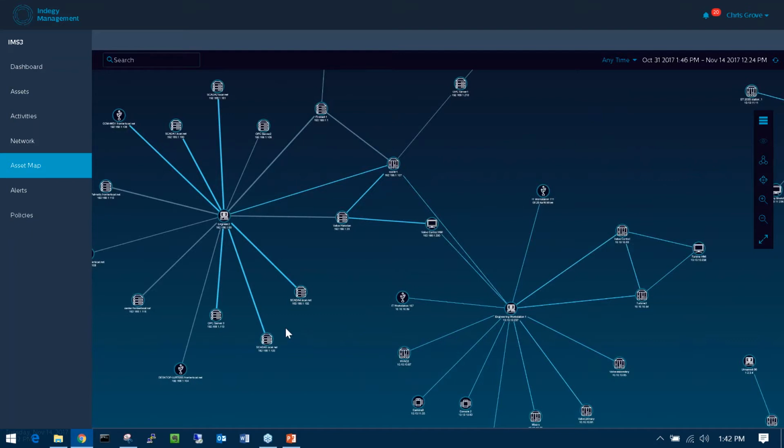If you're not familiar with HMIs, that's the human-to-machine interface. That would be like the panel or the LCD screen, things like that. They also get programming, and they are also usually a high-risk area of a lot of industrial environments. Reason being, some of them run old versions of Windows. They don't get patched. There is also a lot of interaction with them sometimes. There's a lot of people on them.